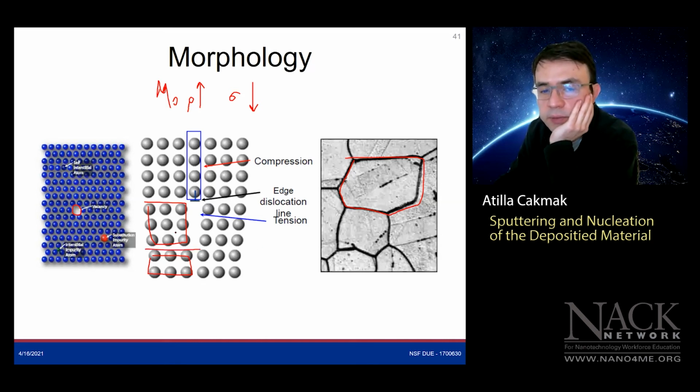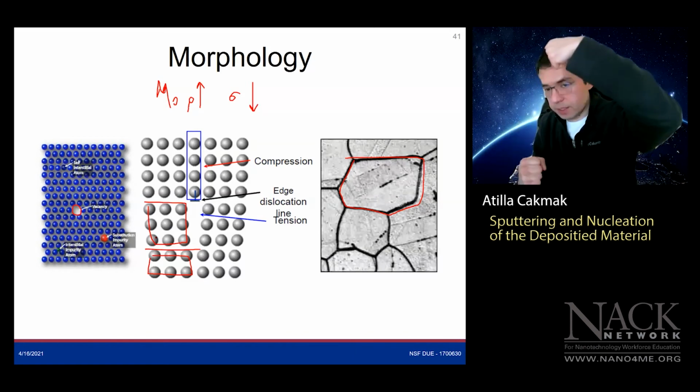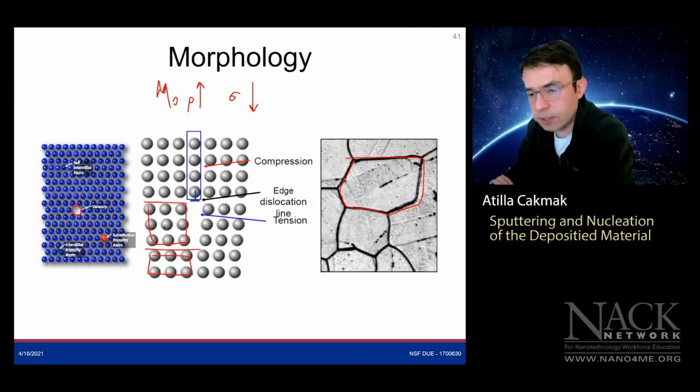All right, I'm just giving a very abstract example here to show you these crystal boundaries. Because of the stacking and how these deposited materials land on top of each other, we might end up with these faulty sites. And what's going to happen? The electron that's starting its journey to conduct electricity will have to channel through these different crystal orientations, and that will increase our resistance. It will add up to the resistance whenever it sees these, and therefore we will see an increase in the resistivity.